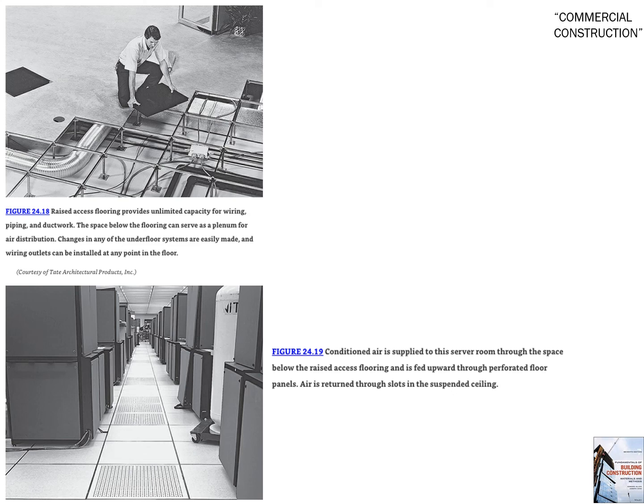You may also have refrigerant lines, electrical power, and more importantly, just blowing air to cool it, even if it's all air cooled now, as it is with the CMOS field effect transistor technologies. It used to be with the bipolar type transistors, you would have liquid cooling because it would burn much hotter. That was the only way you could get speed in the old days. Most of the computer rooms were filled with cooling, air conditioning equipment to cool the computer down. Not so much anymore, but you still need a raised floor.